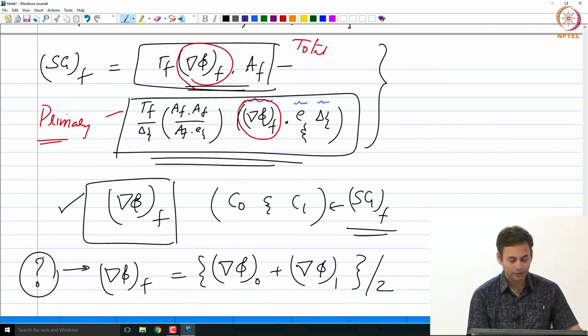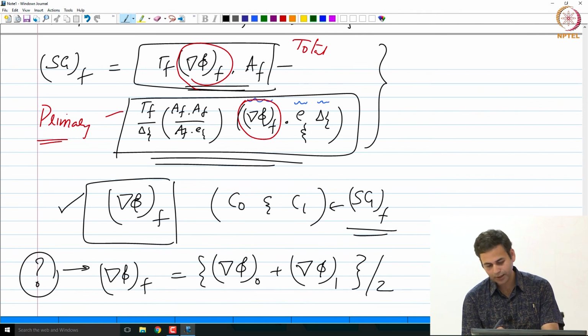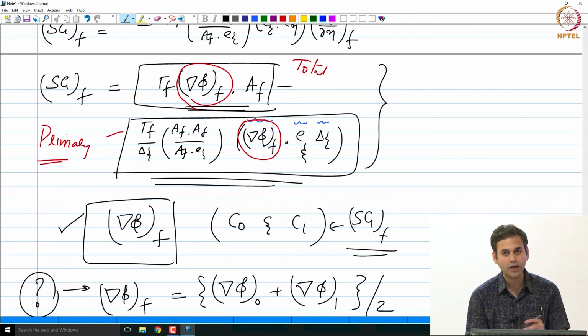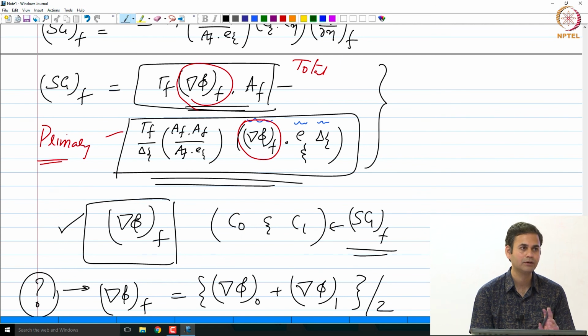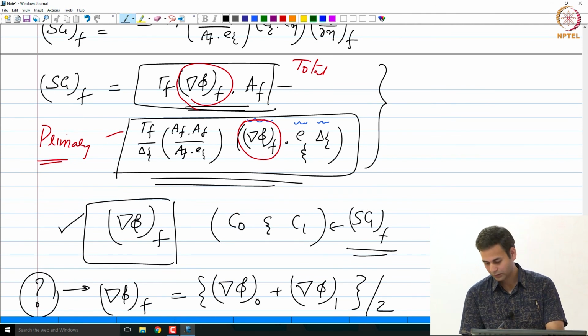Now, there is one more question for you. Let us say we have a linear problem, where the source terms are all linear. We have a constant source term, gamma is also a constant, and we are working on a steady diffusion in 3D with constant source and constant gamma, but our mesh is non-orthogonal. If we have it like that, what is the modification that you have to bring about, or is there any modification?